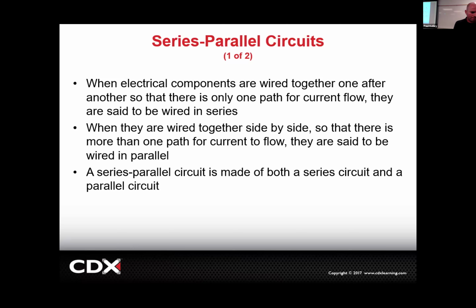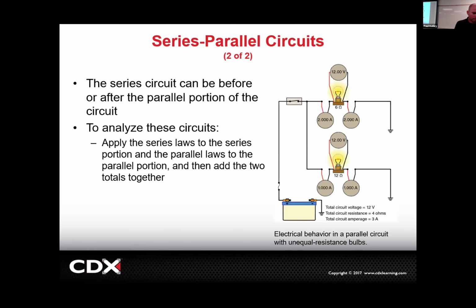Now we got a new one though. A series parallel, which is not really new, it's just a combined, is a part where there's a load in series and then after that loads in parallel. So kind of the same but different. So for example, if we are looking at this, let's trace this, comes off the positive, goes to the switch, goes to this load, that is just simply parallel.